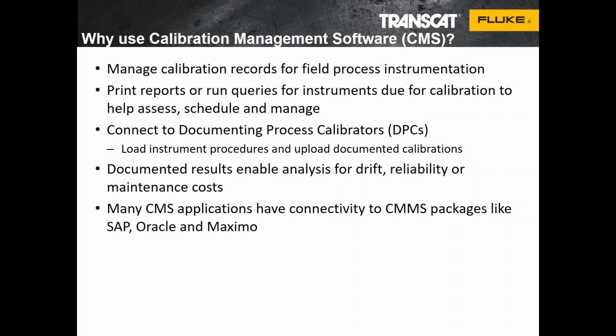So the calibration management software manages calibration records for field process instrumentation, helps print reports, and run queries for instruments due for calibration, helping assess, schedule, and manage the workload. They do allow connection to documenting process calibrators. They can load tasks into the calibrators as well as upload the results. Documented results enable analysis for drift, reliability, and maintenance costs.